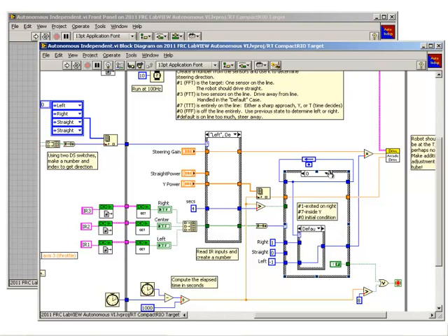The last case, number 1, occurs only when the right sensor is on the line, and in this case the robot will drive straight. We assumed at the beginning of the video that the left case was chosen on the driver station, but the program behaves almost identically in the right and straight cases as well, with only a few minor changes. In the right case, the steering gain is reversed, and so are the infrared sensor readings. This is so that the robot tracks the right side of the line rather than the left. In the straight case, straight power is used instead of Y power for the motor power, and 2 seconds is used rather than 4 seconds to determine whether the robot is on the T or not.